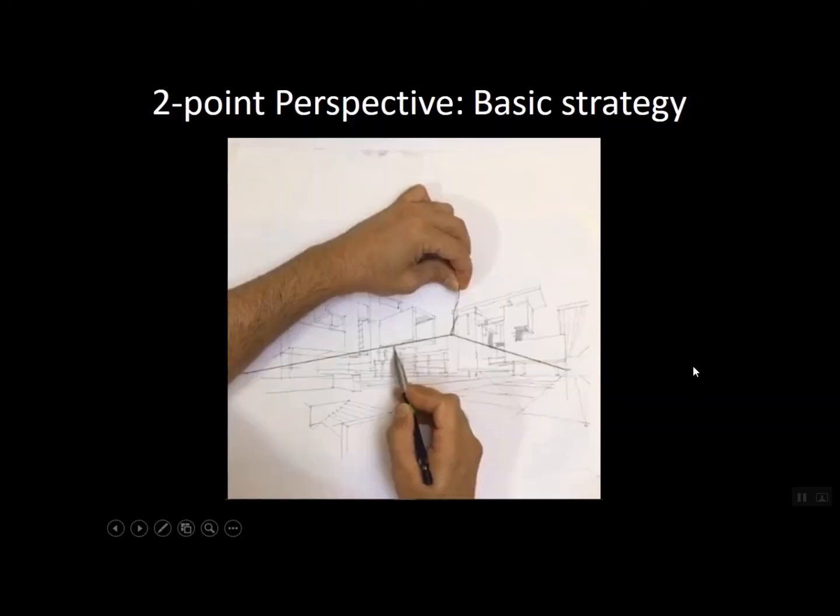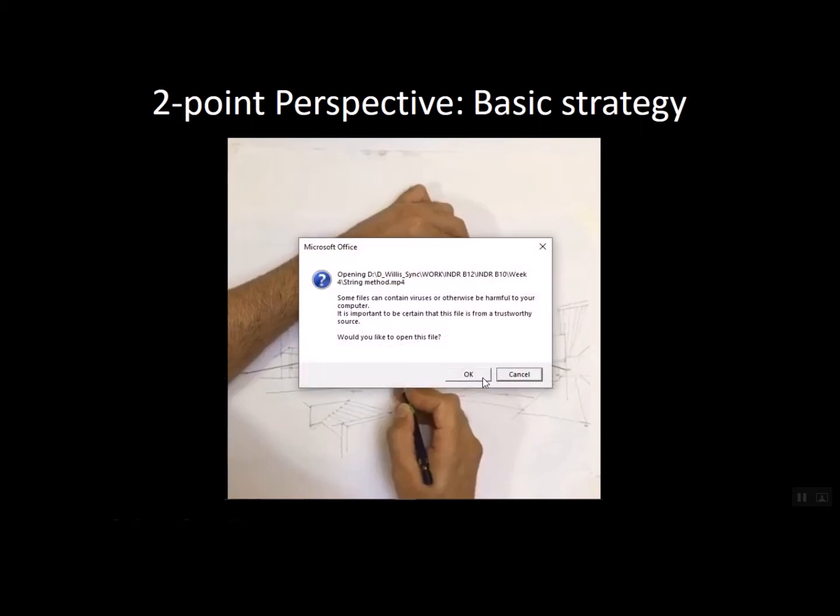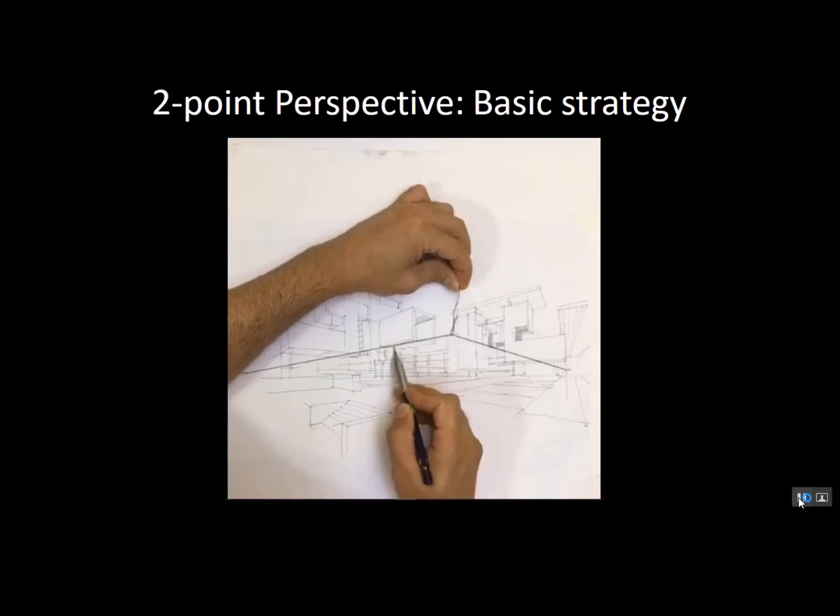There's a lot of ways to do perspective drawing. I've seen people doing it where they have a string pulled up and down by a wire to create these edges that they need to make. And that's kind of cool. I've also seen people take big 4x8 sheets of plywood and put a nail on each corner and then use a stick of wood, like a 1x6, as a guide for drawing their receding lines heading down to that vanishing point. So lots of different ways this has been accomplished.